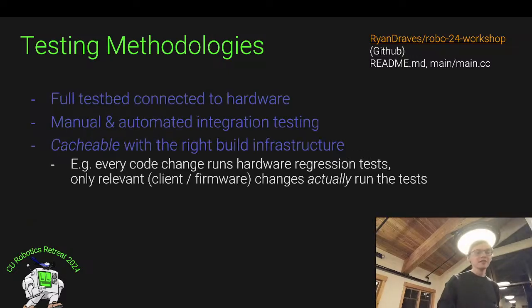So my last thing here is the full integrated hardware testbed testing. You can imagine if we take this little system that you have on the tables there and we plug it into some machine to run automated tests. If we have some block we put in front of it at some fixed distance, we could run an end-to-end test and make sure against the hardware, I request a measurement, is it the right value? I request a lot of measurements really fast, do they all read the right thing, right? And this works pretty well.